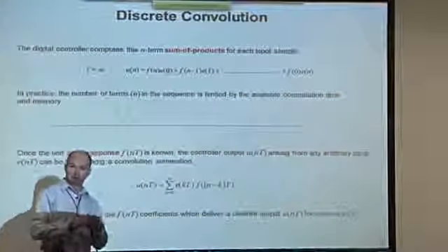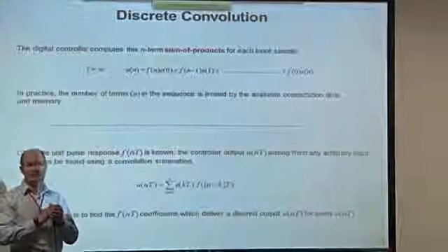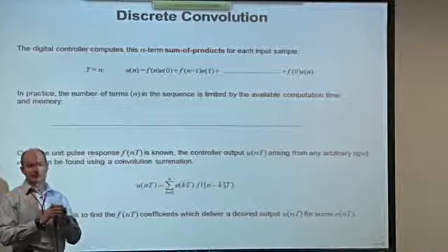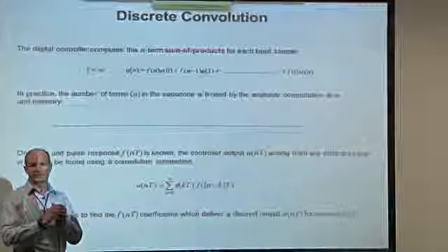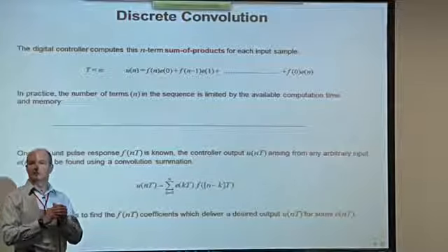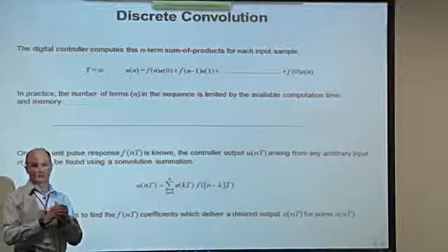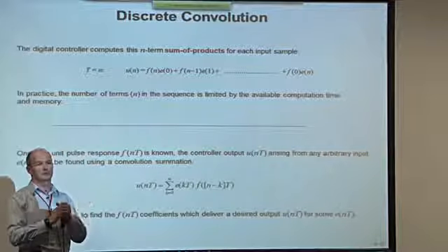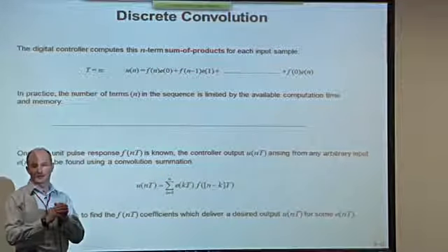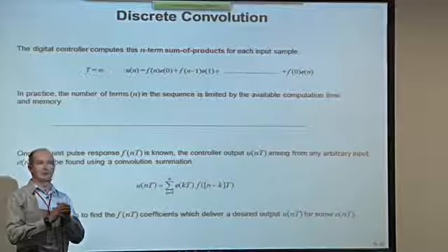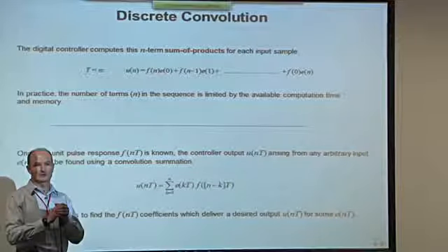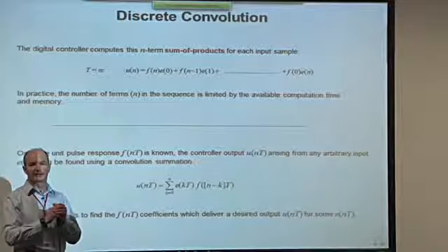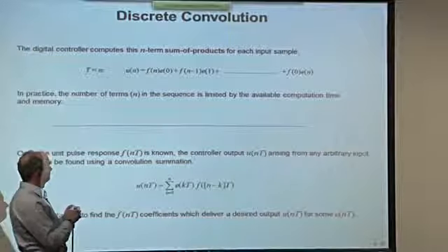Architectures which are good at doing that make very good discrete time controllers. And of course, you probably know that there is an architecture of computer called a DSP, which has hardware which is optimized for doing precisely this. The C28x processor that Ken will tell you all about is fundamentally a DSP. It was the first DSP to be applied to control tasks, and it's still happily doing that. It makes a very good control processor.